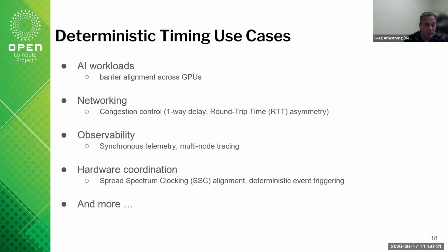It may not even be 1 PPS. You may create a 10K or another, slightly higher frequency to use for scheduling, and say, let's have a guaranteed scheduling slice that occurs at a known time. Or I could create relative scheduling between GPUs by saying, hey, you're going to use this cycle of the 100K clock, you're going to use this cycle, and start staggering scheduling and stuff like that, right? So there's a lot you can do with that marker.